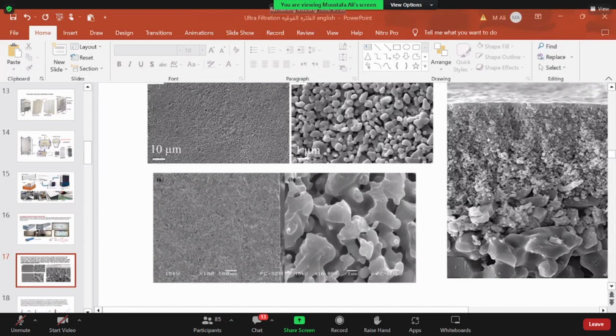This process works because the membrane is very hygroscopic and will immediately suck this solution and leave the particles, forming a surface layer on this coarse layer of silicon carbide. So this is how it's made for silicon carbide membranes.